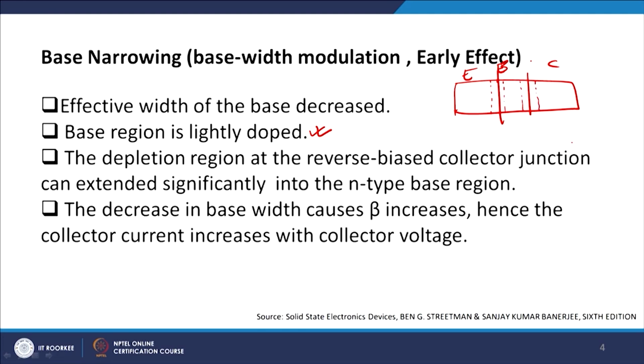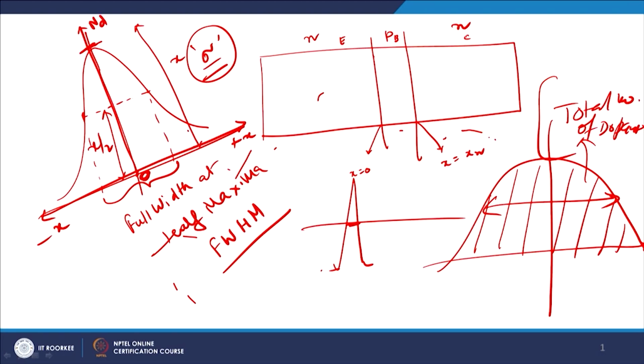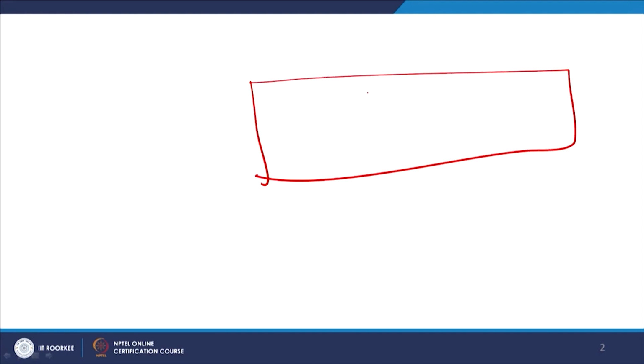But as I have told you previously also, the depletion thickness will be larger towards the region whose doping concentration is low, right. So, if I have a PN junction or maybe an NPN transistor, which is a BJT, and let us suppose this is emitter, base, collector, and since the base is relatively lightly doped, I would expect to see the depletion regions something like this.